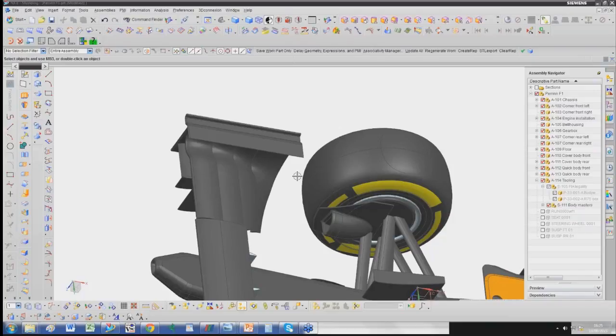Junaid wants to know if dynamic pressure is as important as static pressure for your result evaluation. Both are very important. You want to look at both. The static pressure is really the result. It is the pressure that is applied on the surface of the car. So this is the consequence of everything. Okay. What is the static pressure that's creating the downforce? So this is like the result, and you sum the pressure and you get the force on the car.